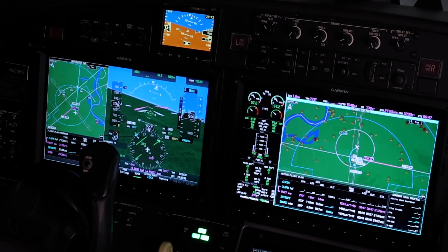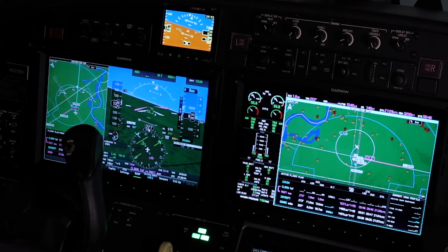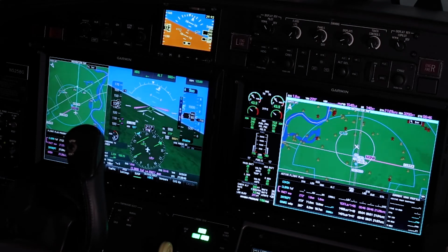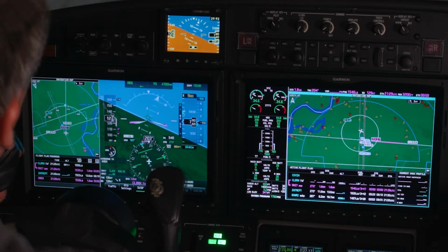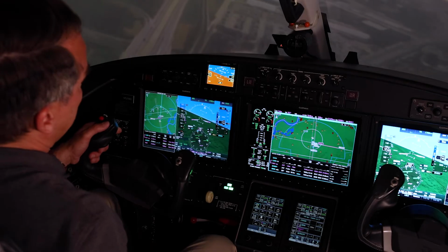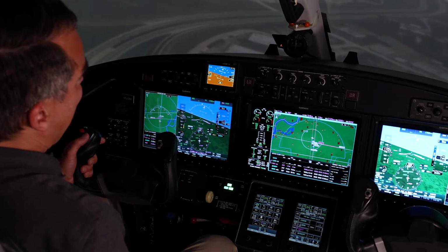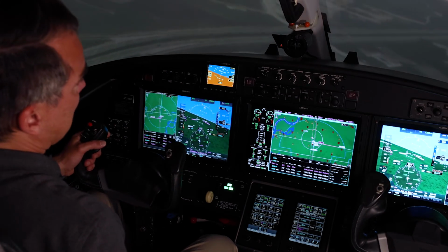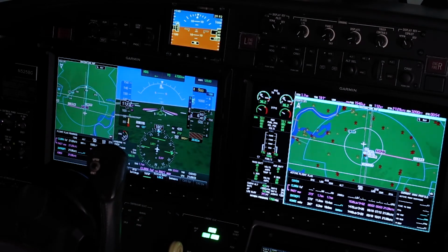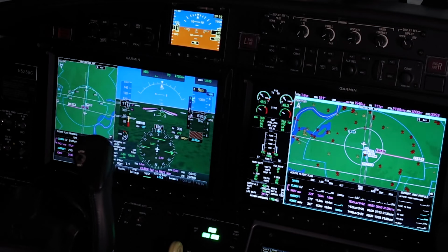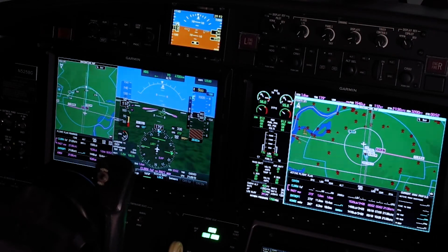As I start my descent, I'm going to remember that the selection of the landing flaps will have a tendency to make me balloon. So I can select vertical speed down 500 feet a minute, 600 feet a minute. That's going to help keep me descending. Again, remembering that a common error is to end up too high. As I'm wings level on final, I can slow to ref. I want to be holding at least ref plus 10 with the landing flap selected through that final turn to give me a little bit extra margin over stall as I'm banking 20-25 degrees.